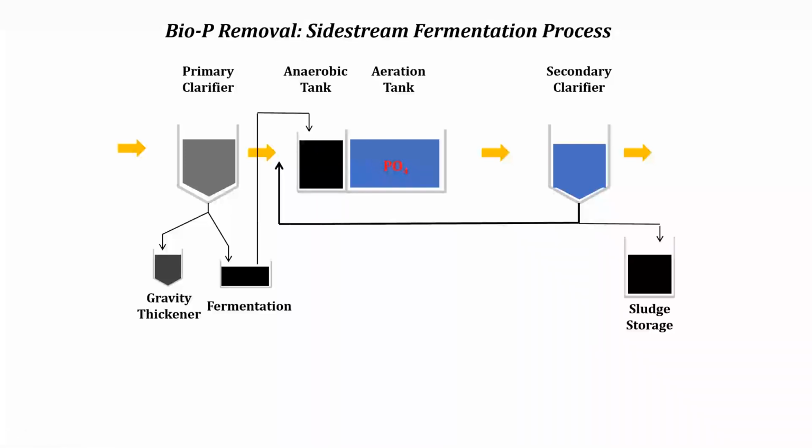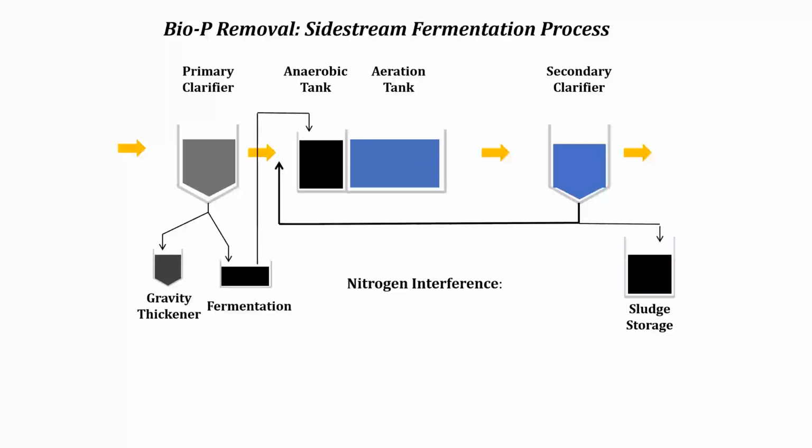The soluble phosphorus, along with the energized organisms, flow into the aeration tank. And given the right conditions, they're going to multiply and remove the phosphorus from solution. Pretty nice because now you can manage your VFA input and make sure that you're providing enough of that candy to support energizing the phosphorus removing organisms.